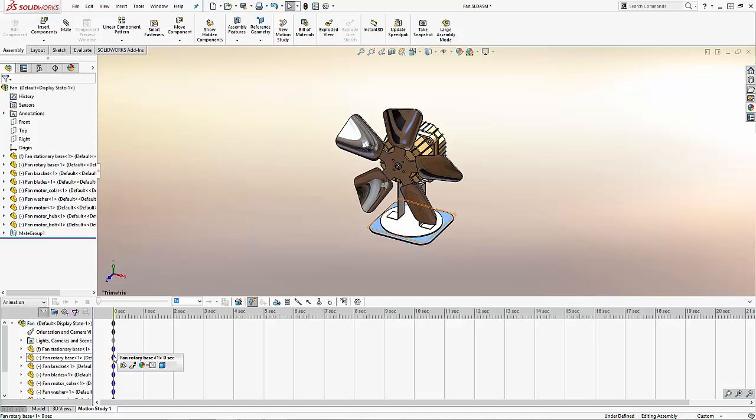Now let's define what defining a motor in SolidWorks means. When you define a motor, there are 3 inputs that control what is actually moving. The first thing is the motor location, the components to be moved by the motor. Second, the motor direction. The motor direction is defined by an edge or axis. And the third one, the components to move relative to.